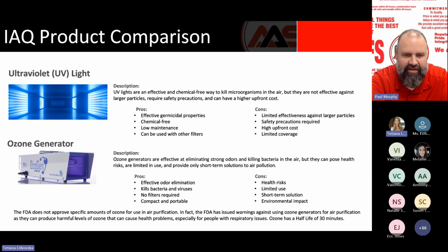But we don't use it for air cleaning, because air systems have air flowing through them. Your standard 5-ton is 2,000 CFM, so the air moving through is not going to be exposed to that UV light for more than a second at all. It'll only be a couple milliseconds. So that being said, we use them to keep coils clean, keep drain pans clean. That's what they do a good job on.